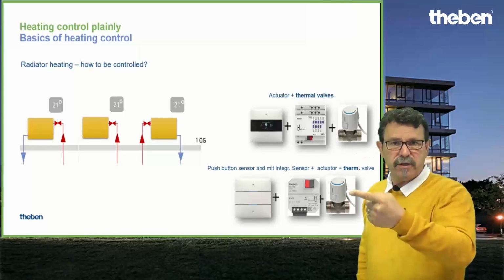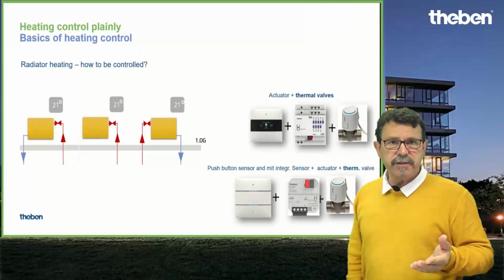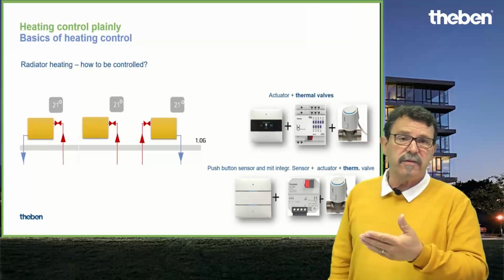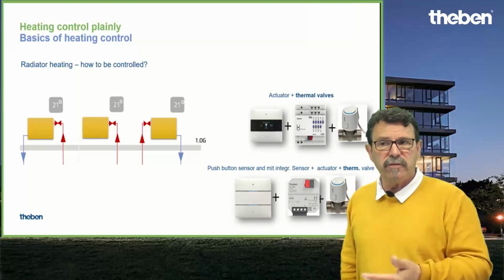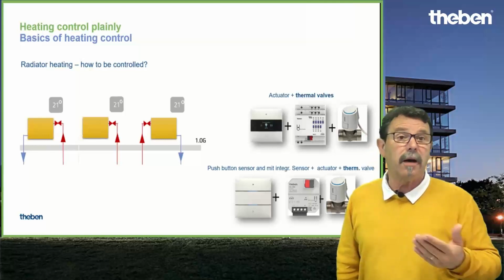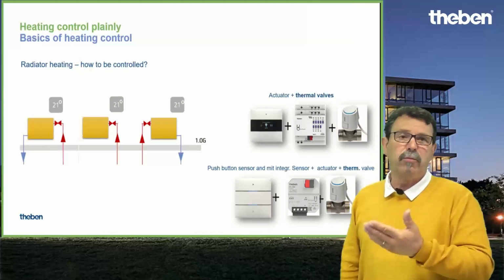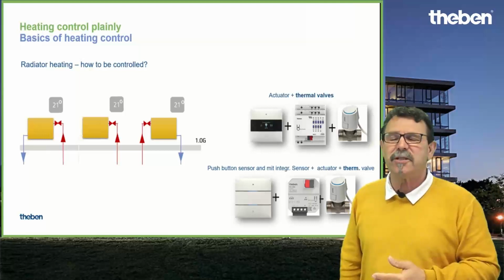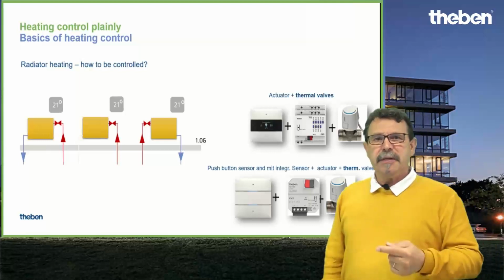So the valves, it's your decision which you want to use. However, it's a matter of price as well. Thermal valves are by far cheaper than a motor-driven valve. Motor-driven valves are by far more accurate than a thermal valve. So it's up to you what you desire, what your client desires to have.